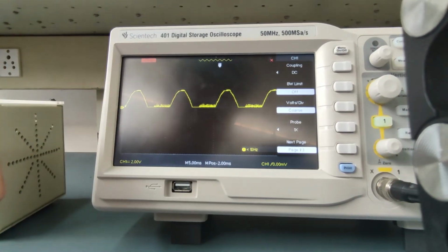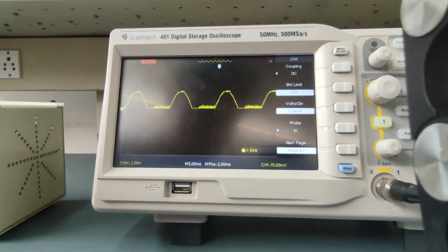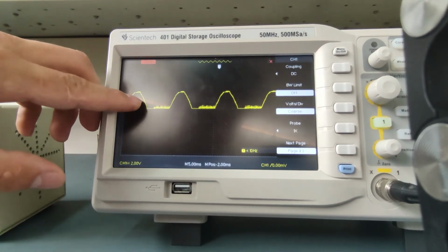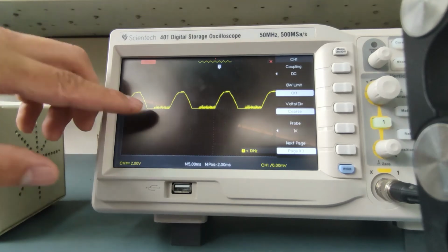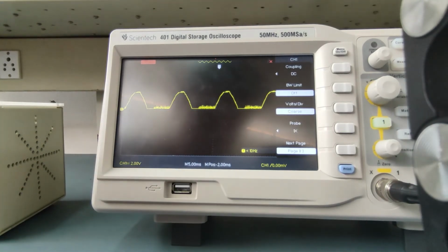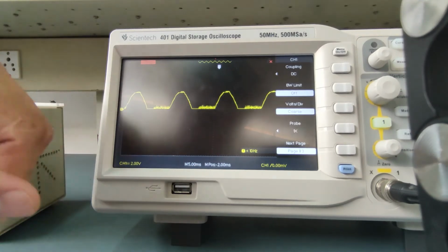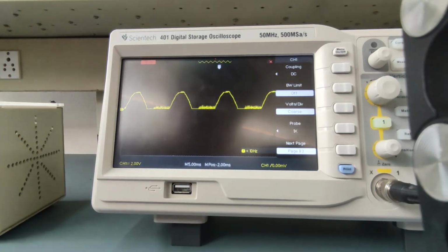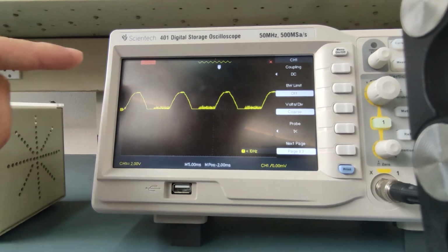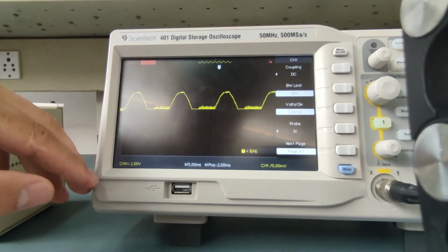And for the freewheeling diode, when the supply voltage is 0, the nature of load will cause the current to degrade slowly, which will drive the diode in forward bias. But when the freewheeling diode is connected, the freewheeling diode will act as forward biased and be short circuited, and as a result all the current that is stored in the inductive load will be passed to the freewheeling diode, and the output waveform will be much more smooth.